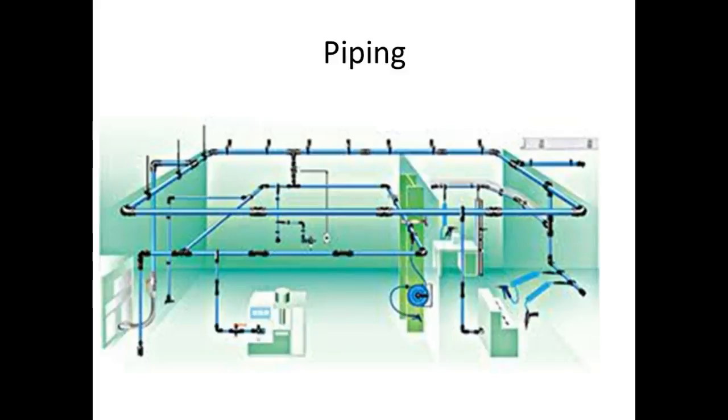So my valve, if there's no motion, if there's no flow, then pressure in and pressure out of the valve would be equal to each other. But as soon as you have flow, the output pressure on the valve will be slightly less than your input pressure. And that's what the Cv rating of the valve tells us. It tells us the pressure drop across the valve at a certain area and a certain flow, right? That makes sense?